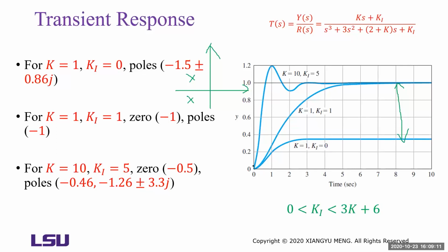When k is large, this error will be small. We can pick k very, very large to be very close. But the tracking error will never be 0, no matter how large the k is. The unit step is our reference.